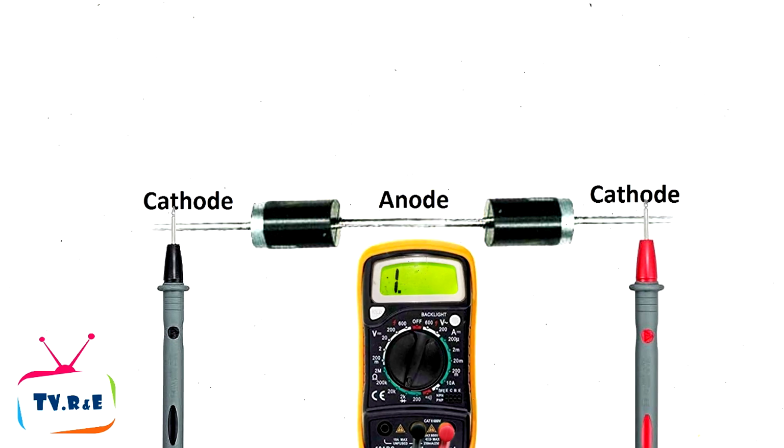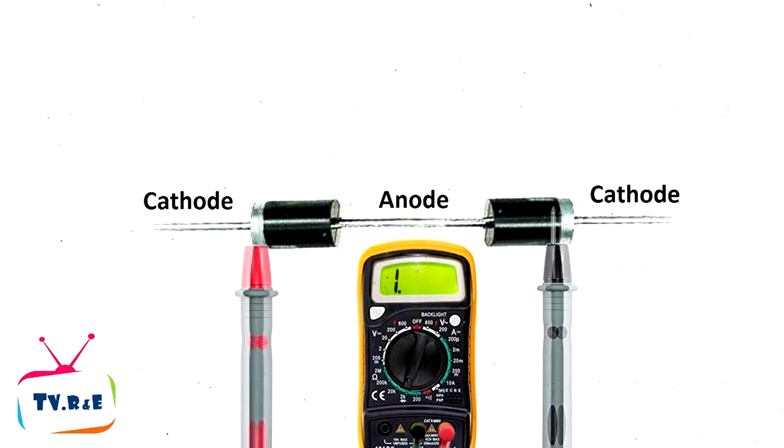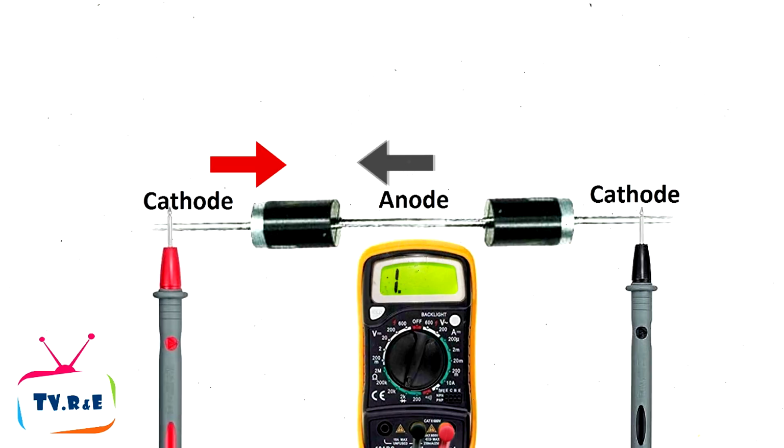That's because a rectifier diode allows voltage to pass from only one direction. Due to the rectifier diode allowing voltage to pass from only one direction, the voltage coming from the multimeter gets stopped and we do not get any kind of reading, even if we switch both the leads of the multimeter.